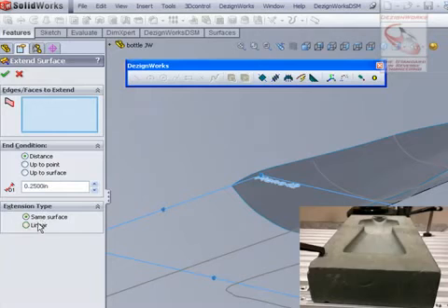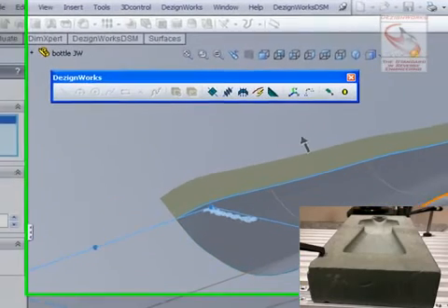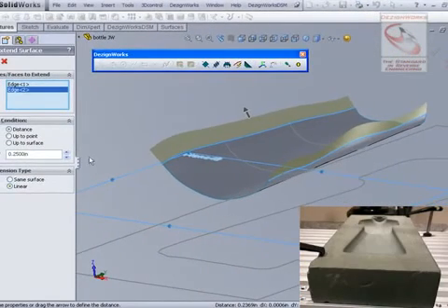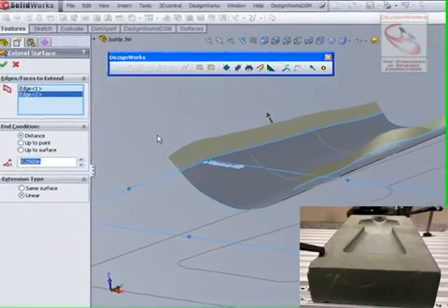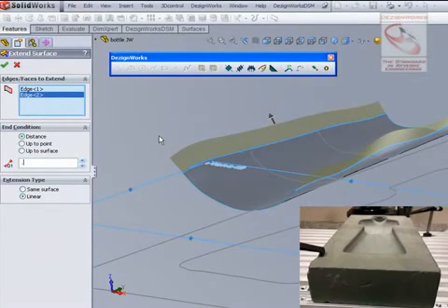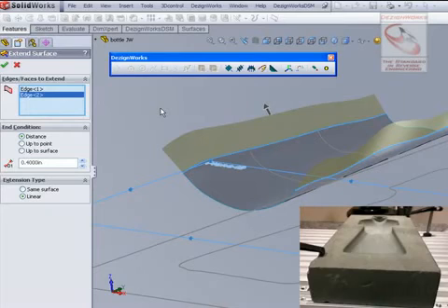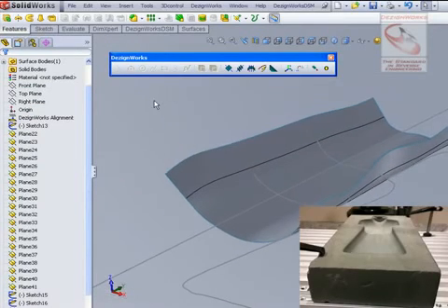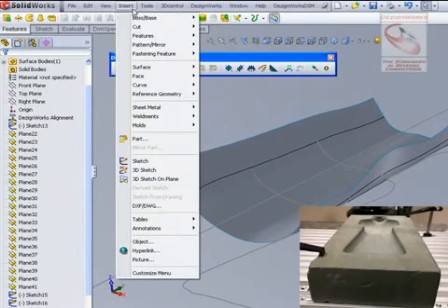We're going to select the surface edges to actually extend. And we'll extend these up at least the diameter of the ball, so we want to trim them. So I'm going to go ahead and make it a little bit larger here, so we can trim this. Now that we actually extended these, we can use the Solidworks trim tool to trim them back to get the exact shape of the edges where this is at.